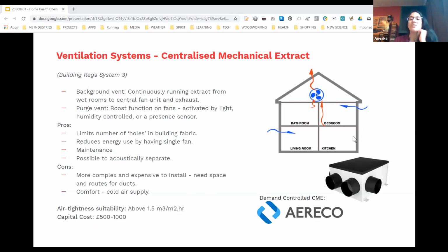So I guess that in terms of the more complex systems, for example, I'm going to talk later about MVHR, mechanical ventilation heat recovery, if a system's more complex and more expensive and your house is very drafty, it might not be as effective as it would have been, which might mean that you've not spent your money well. If the system's less expensive and less complex, even if your home isn't very airtight, it will still do a job. That would be a worthwhile job to do.